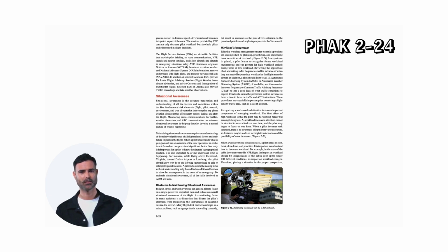Situational awareness. Situational awareness is the accurate perception and understanding of all the factors and conditions within the 5 fundamental risk elements: flight, pilot, aircraft, environment, and type of operation that comprise any given aviation situation that affect safety before, during, and after the flight. Monitoring radio communications for traffic, weather discussion, and ATC communication can enhance situational awareness by helping the pilot develop a mental picture of what is happening.